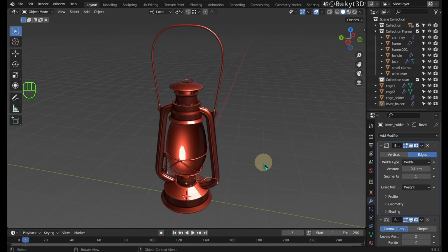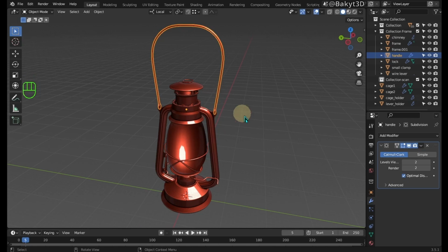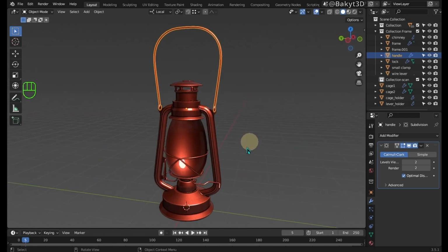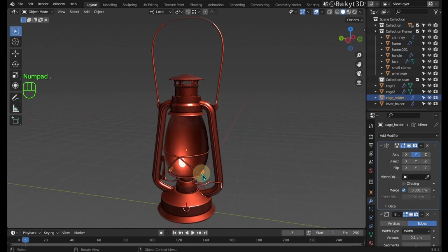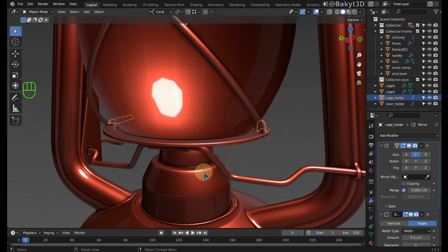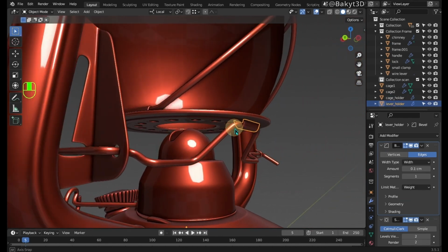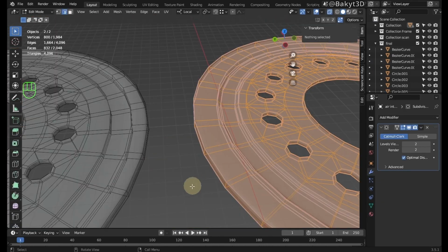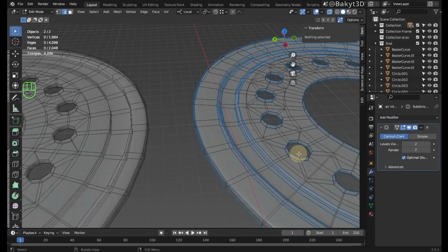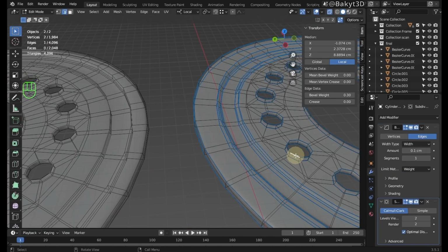Let's prepare a high poly model of the lantern for baking its details into a low poly one. Before explaining what was done, I want to show a few more details that are simple yet still add some realism, which were modeled using the methods described in the previous tutorials. In cases like this, I reduced the number of faces and applied mean bevel weights, and added a bevel modifier, so that later I can quickly switch to a low poly model by simply cancelling the modifiers.